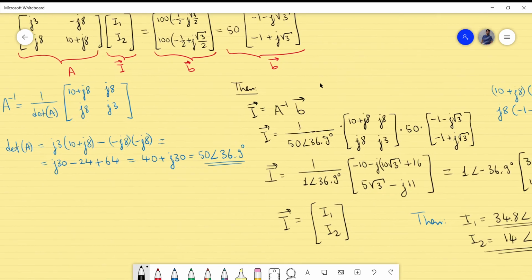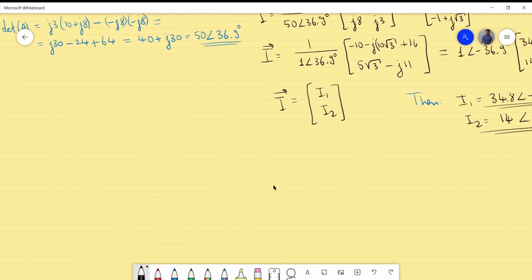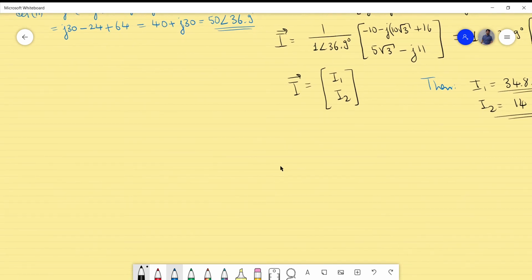So if I now write down the load currents, first the load currents, I will do that here. IZ of A for the first one will be minus I2, IZ of B will be I2 minus I1, and IZ of C will be I1.